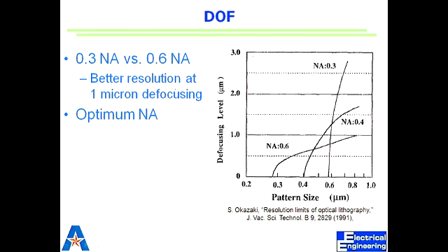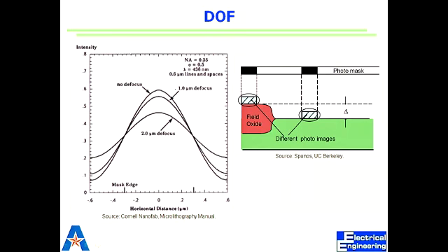Now that we are doing shallow junctions, does that matter so much? Shallow junctions, like the source is very close to the surface. So of course, if your depth of focus is not reasonable enough, and your feature is on that, you are making contact to source, for example, you will get exposure which will be much more wide than what you would have got with this guy. See the intensity? You have much more intensity now. Do you see what I'm saying?